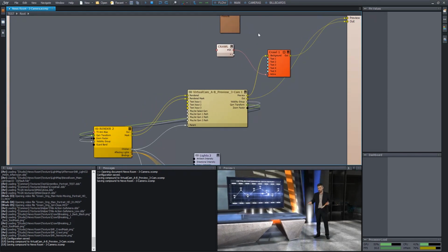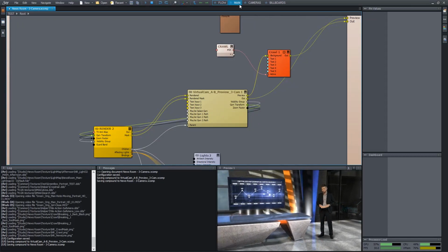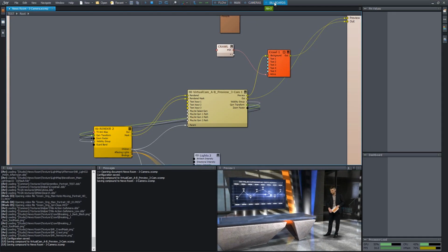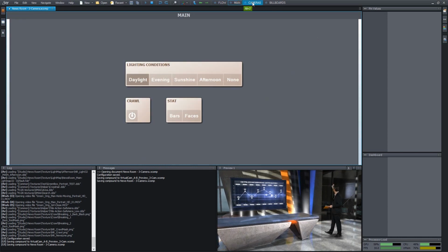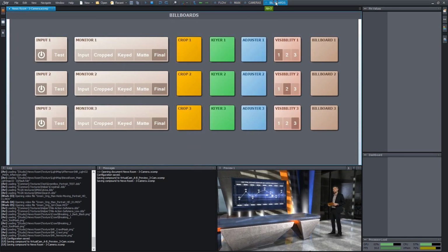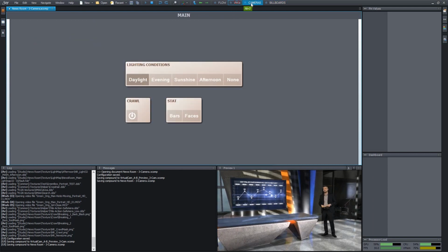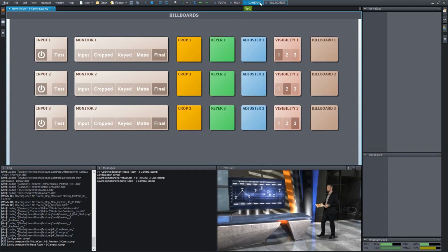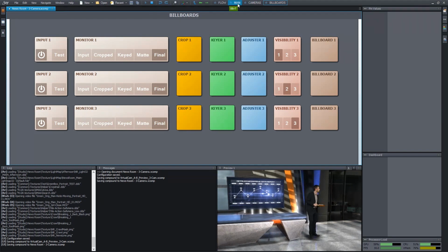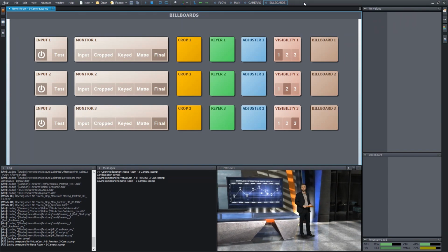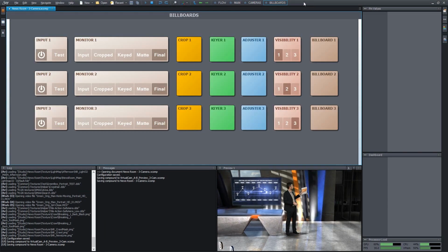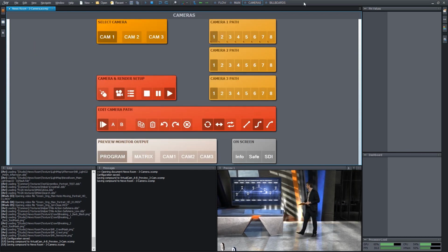The things we are going to focus on now are the so-called control boards. These can be selected and changed between here and in the toolbar at the top. In this configuration, we have access to 3 control boards. We have several options to change between the control boards. One is to click on the top of the toolbar and alternate between them by pressing Alt-1, Alt-2, or Alt-3, or by repeatedly pressing the F2 key on the keyboard, choosing the next control board in the sequence.